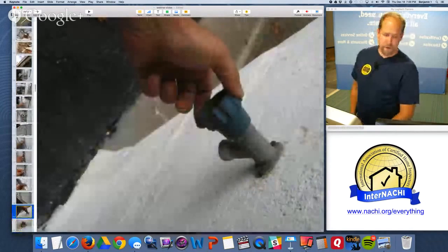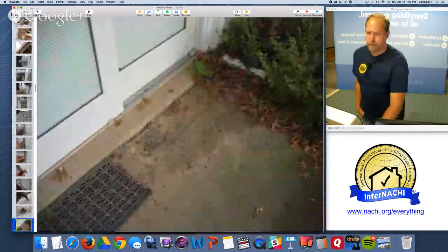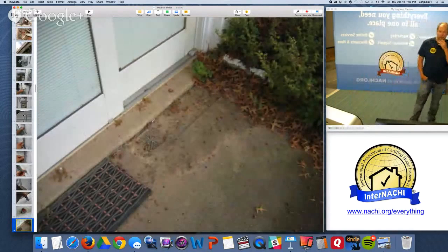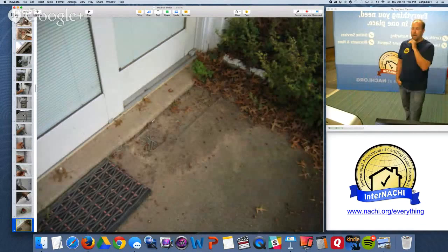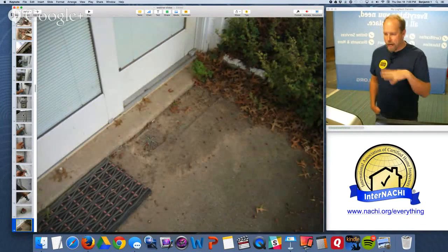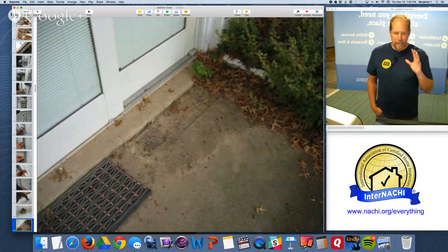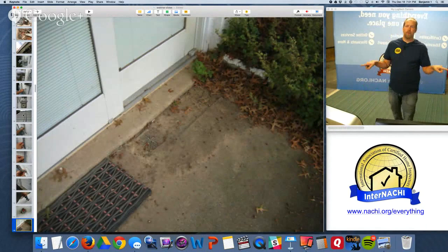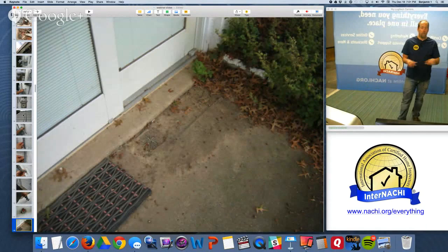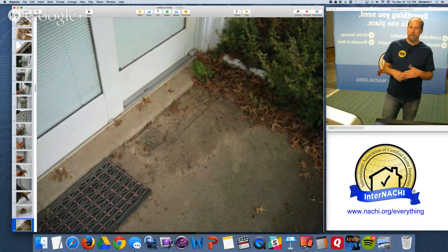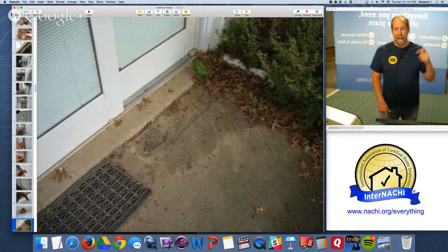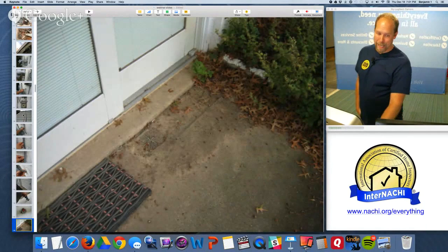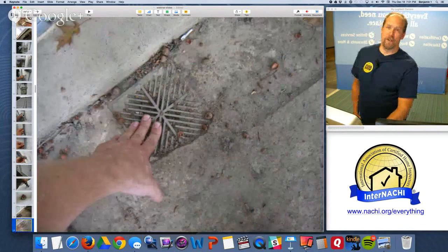Exterior water faucets are frost-free. That's great. No GFCI receptacle on that one. There's a drainage ditch, drainage pipe right there at the basement door. You could see that mud puddles up there, water puddles up there. They have water problems in this house. I have a garage door with a bunch of holes, poorly designed, poor workmanship, probably doesn't perform very well to stop water from entering the garage. I have a drainage problem here, so I added a drain to this existing concrete slab, and it's filled. It's just clogged.